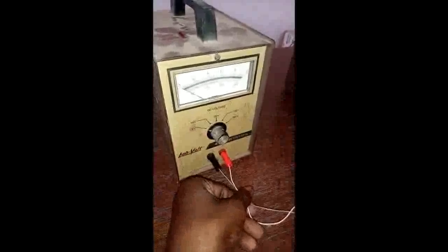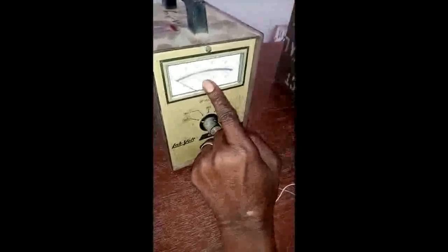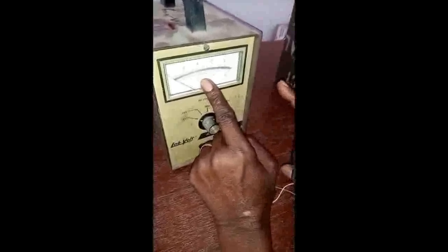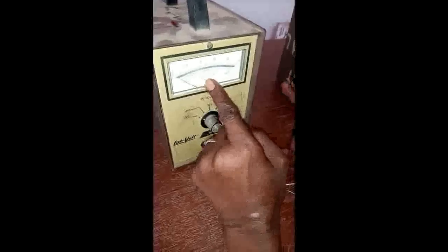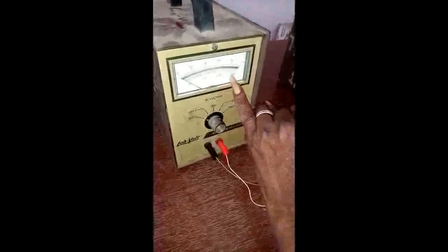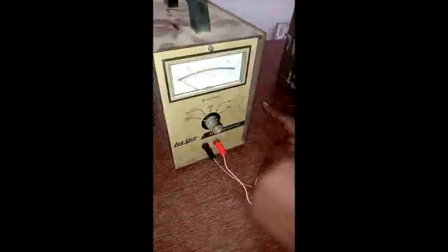3 volts. Now, if you connect this into the circuit, and the pointer just right from here and rest at 10 here, at the back of your mind, since you know that you are going to divide whatever you get there by 10 to convert this to 3 volts, then this 10 here will now mean just 1 volt. So if it goes to up to 20, that 20 will just be 2 volts. And vis-a-vis when you get to 30, that is 3 volts. That's exactly how to use it without any wahala.